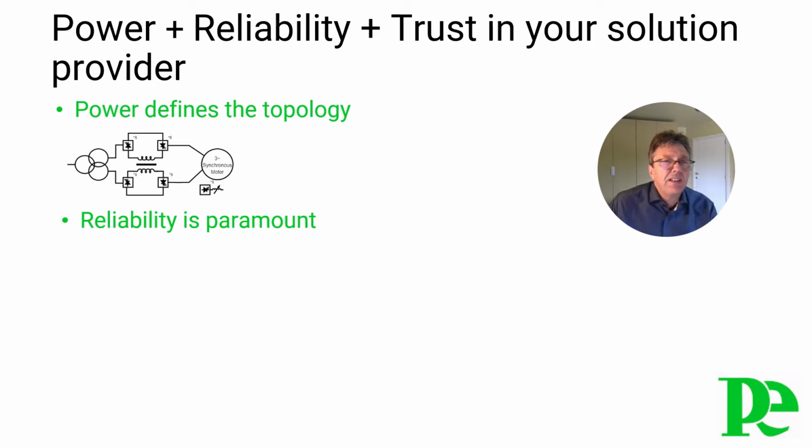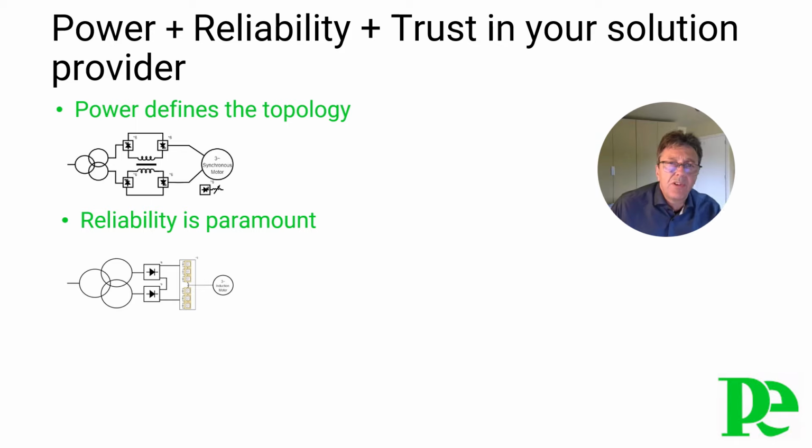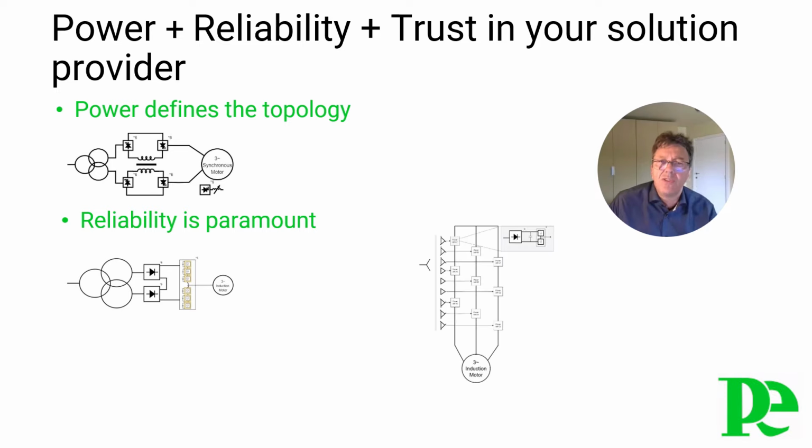Reliability is paramount. Cell-based topologies, including modular multi-level converter and the two-level series-connected H-bridge cells, utilizing low voltage components, N+1 redundancy and film capacitors, typically offer superior reliability. The LCI technology is also highly reliable thanks to its robust thyristors and numerous proven applications in various fields.